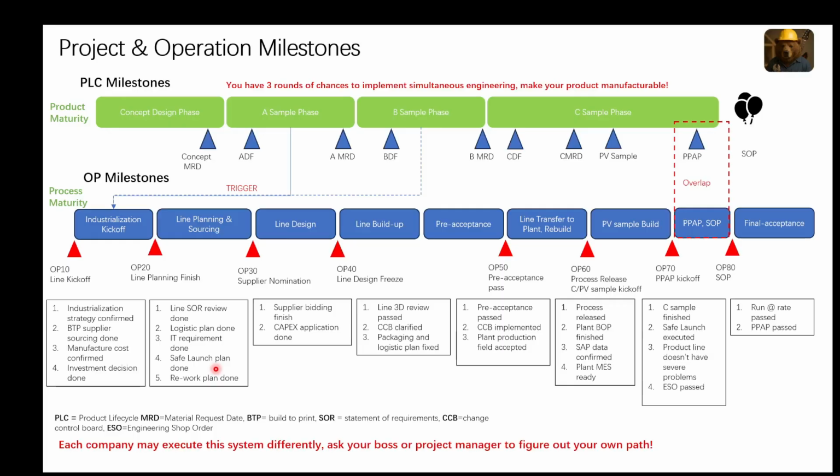In the early manufacturing phase, you need to put a lot of extra measurement or extra activities to make sure that the product is designed according to the quality requirement, or fulfills your quality requirement. So we call that phase safe launch plan, because this safe launch requires more measurement devices or more effort. So there's a cost in it. So you need to plan it carefully.